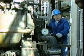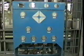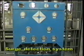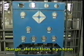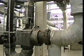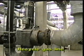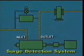That's why you'll find most compressors use a surge detection system. The surge detection system senses discharge pressure variations and initiates a compressor shutdown in the event of a potentially serious condition. A surge control system can also be installed that allows discharge gas to be recirculated outside the compressor to the suction side. The objective here is to keep the flow above the surge point.